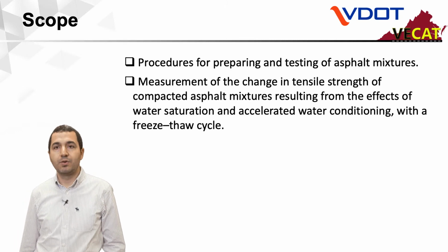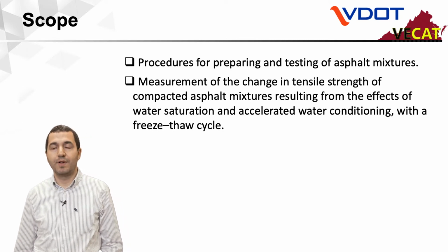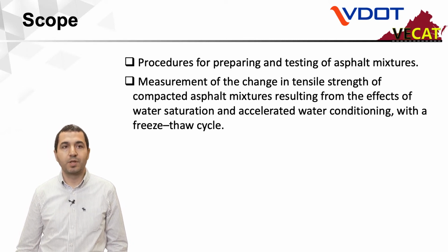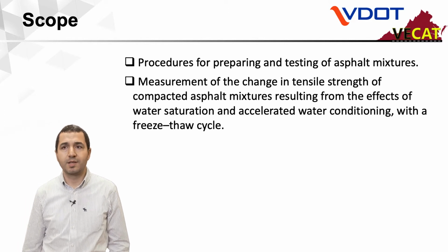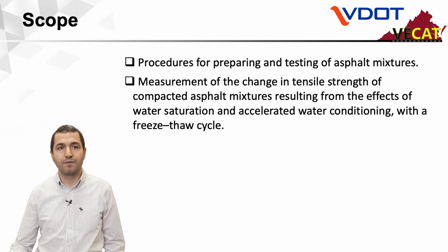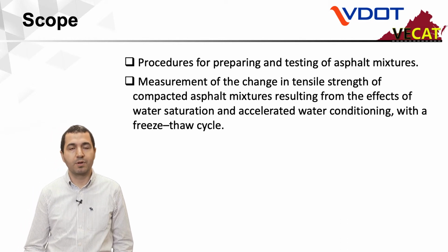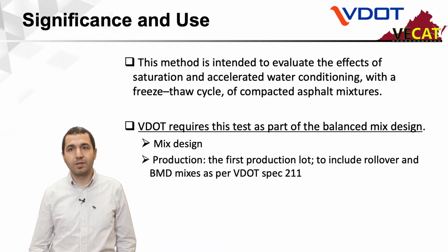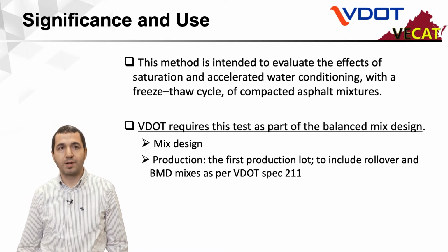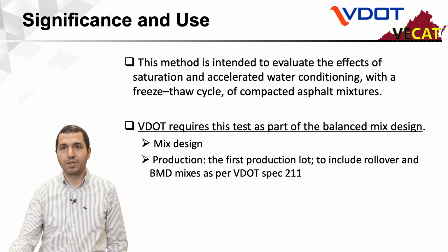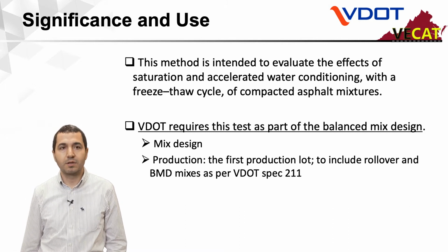Scope of this test includes procedures for preparing and testing of asphalt mixtures, as well as measurement of change in indirect tensile strength of asphalt mixtures resulting from effects of water saturation and accelerated water conditioning with a freeze-thaw cycle. This method is intended to evaluate the effects of saturation and accelerated water conditioning, or moisture damage effect, of asphalt